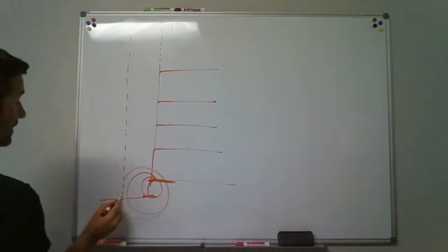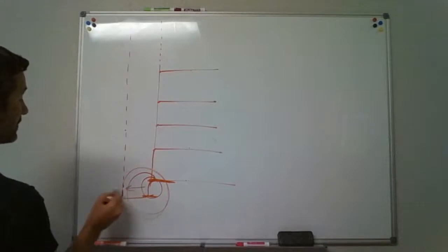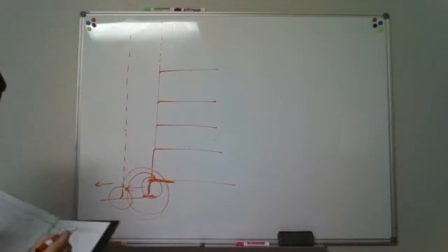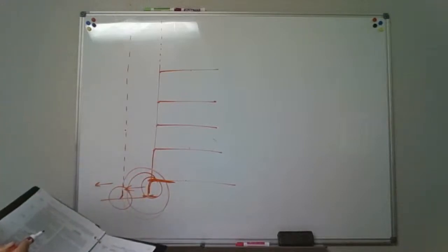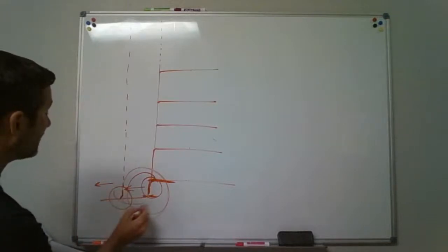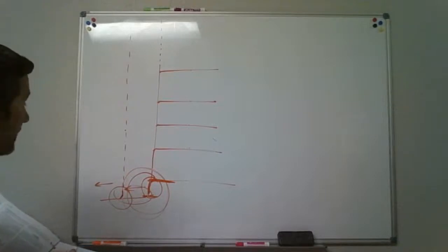So it says, yes, we can connect it to the building drain, but everything's flowing this way, so it needs to be downstream of the stack. All right. And it says, and within, so as far as within 10 times the diameter of the drainage stack.